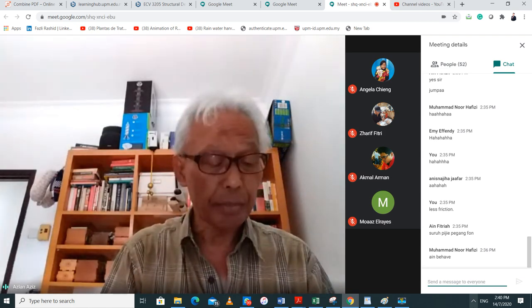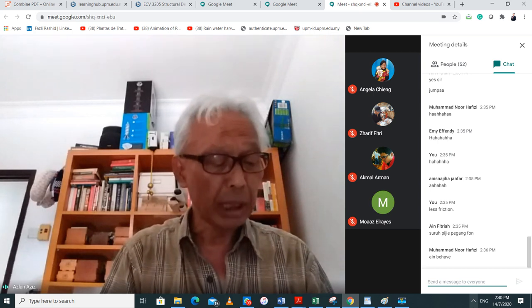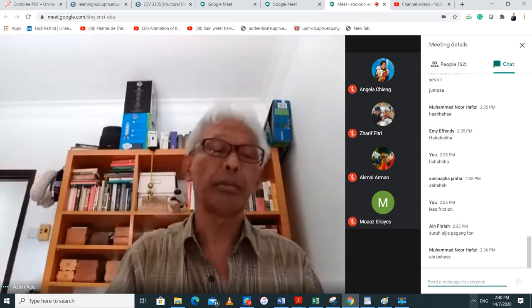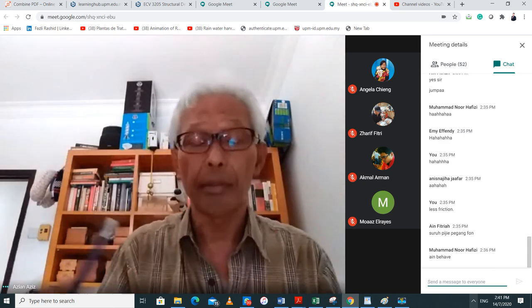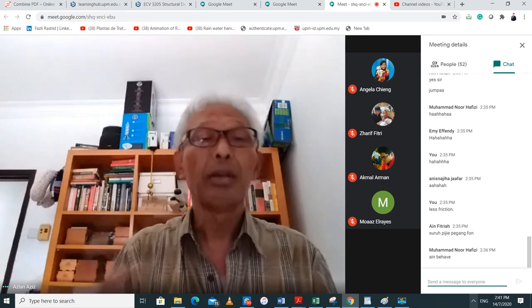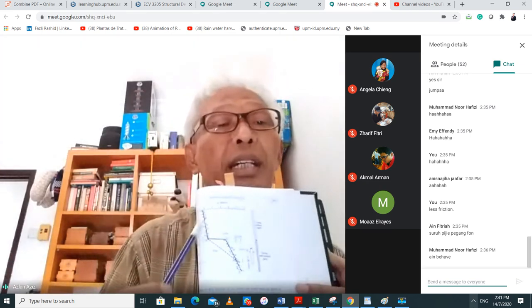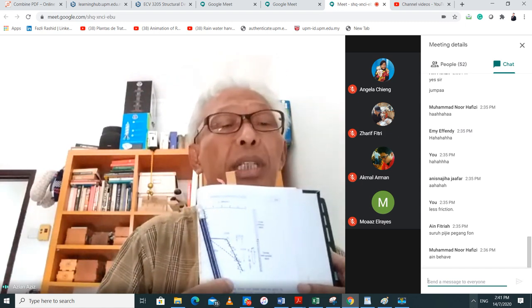Then it says, by inspection of figure 8.25, the cone resistance is fully developed over a depth Y sub C of 0.3 meter. Now you look at figure 8.25. Like I said, there are two layers there. One is the loose uniform sand, the other is the dense sand. For the loose sand, you just draw a straight line through it, take an average value.